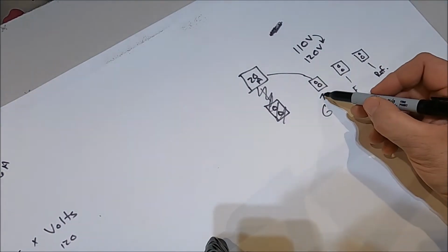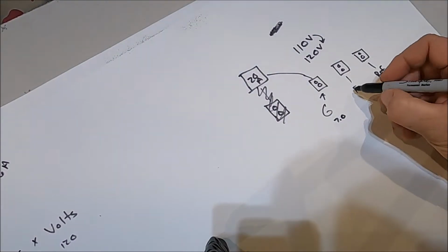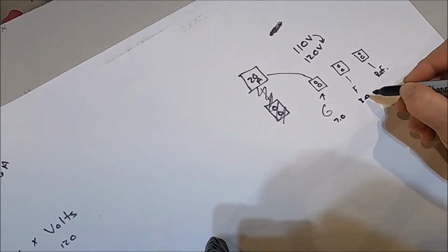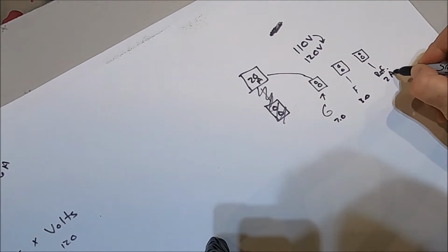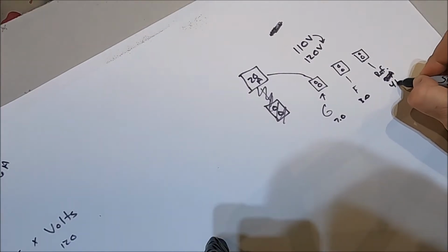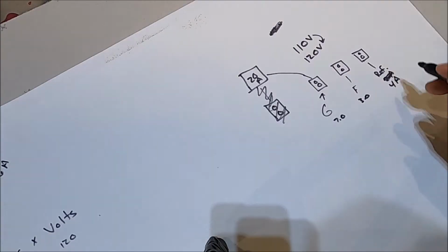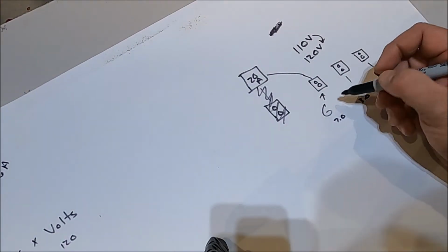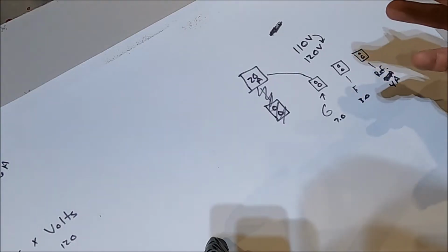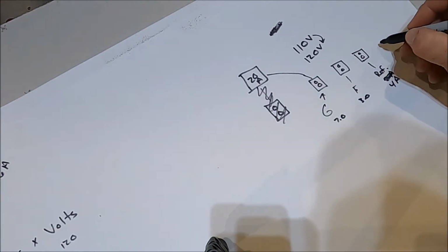So if I'm going to sit here and use my grinder, let's say a grinder will draw about 7 amps. Let's say the fan running draws about 3 amps, and the refrigerator, let's just call it 4 amps. So we're about 14 amps, so we're well within the 20 amp, even though this is constantly running, this is constantly running, and then I'm going to turn the grinder on, use it for a little while, and then stop. So a few of these things I can have plugged in, no big deal.